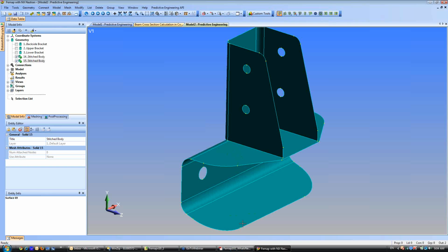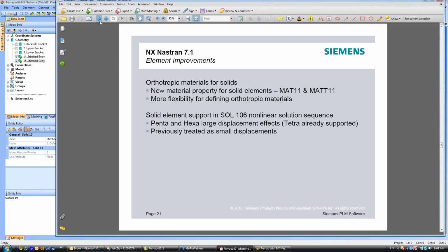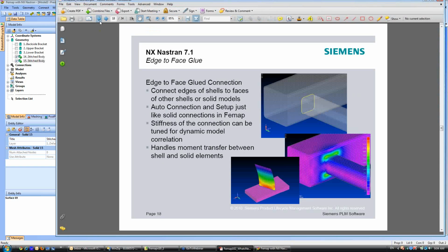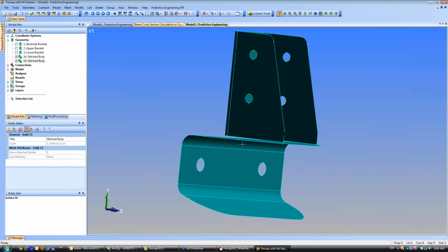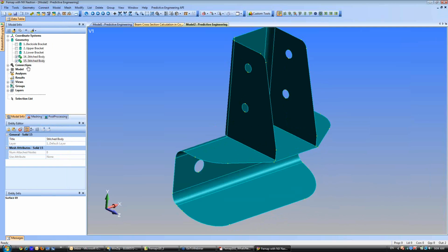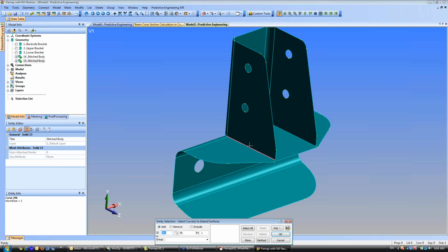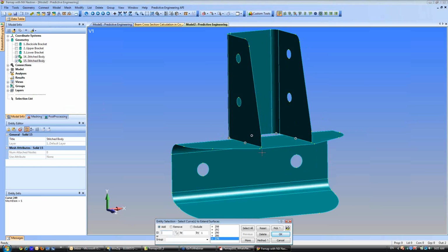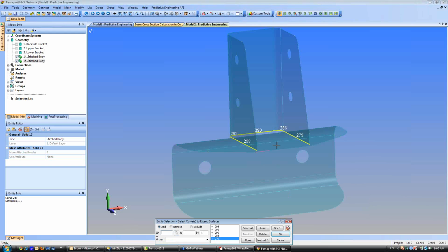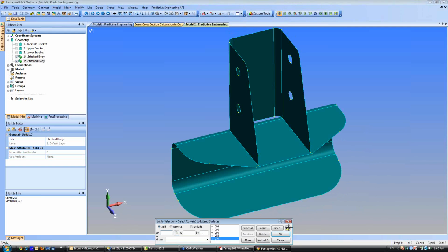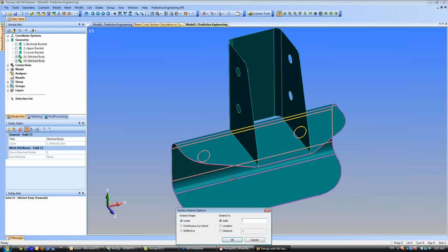Yes, I could take this demo and do the new edge contact thing, and show how you can make an edge contact with this model. You don't need to extend, but I want to make it continuous because this is a welded part. So then I'm going to go back to geometry, mid-surface, extend, pick, and then I'll verify here. Yes, those are the curves I want to use. I'll hit that thing again. Hit OK. I want to extend them to this solid down here.